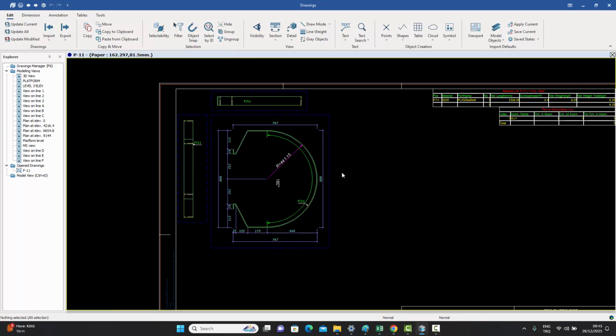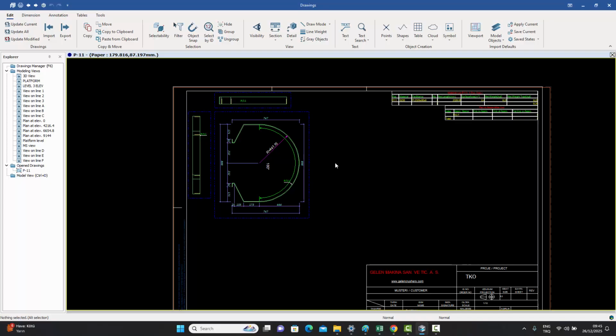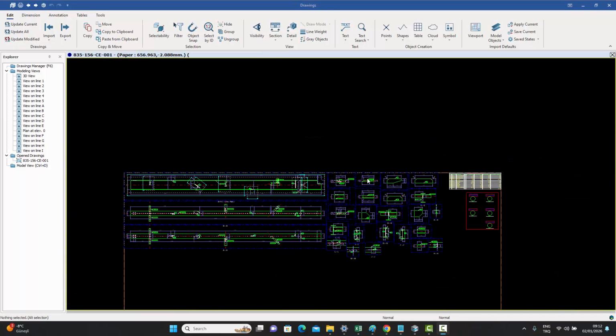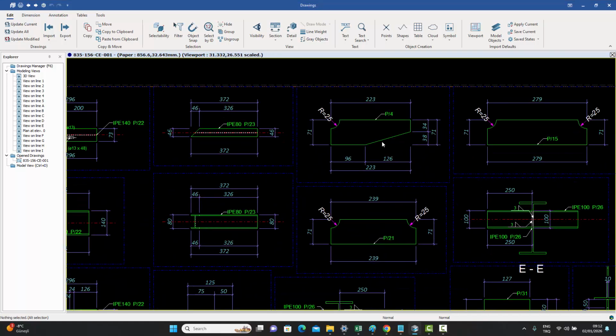So this is a very nice feature to have whenever you see that something, because of its own internal dimensions, is using a different coordinate system for dimensioning than the one which you would have preferred. You can give it this angle rotation and create a new drawing based on that. And just like we can rotate views in the single part drawings to give a better dimensioning, we can also do the same in assembly drawings for particular single parts.